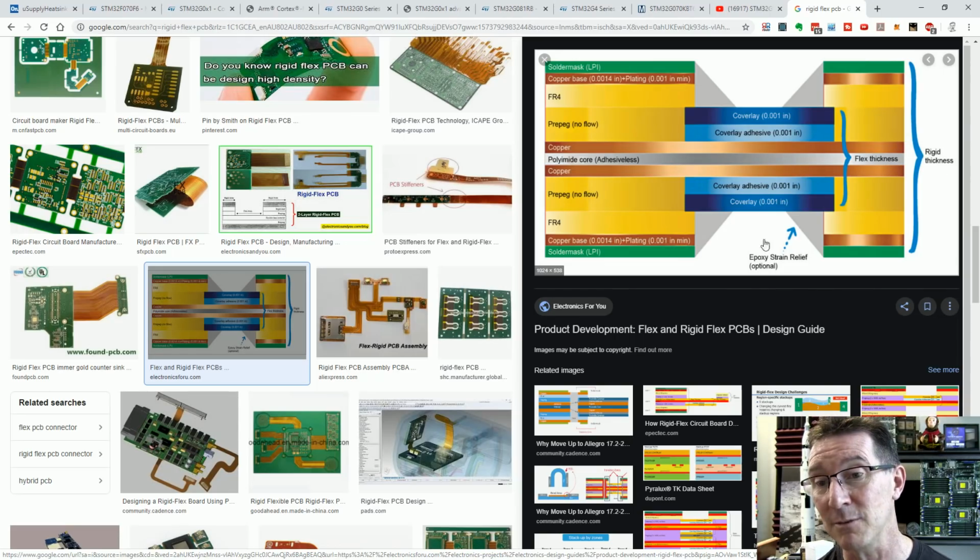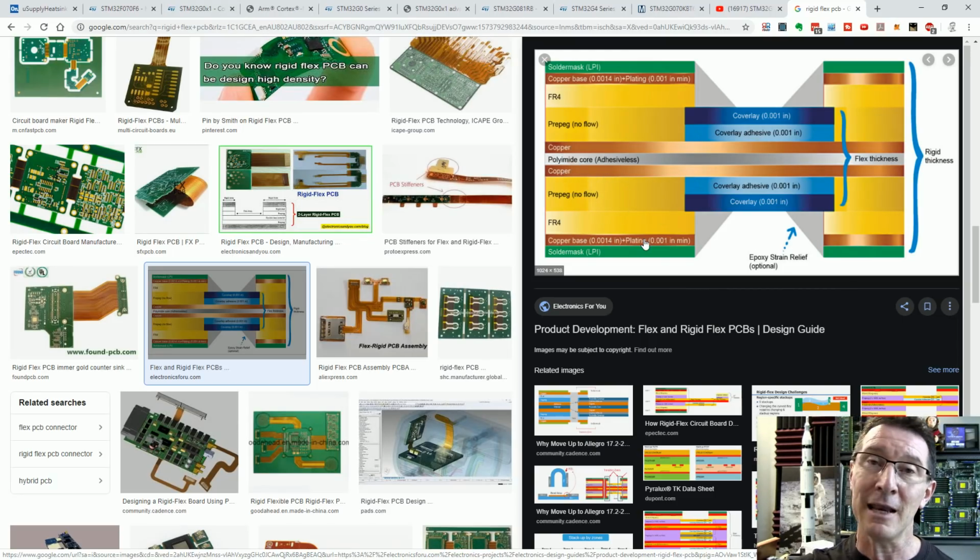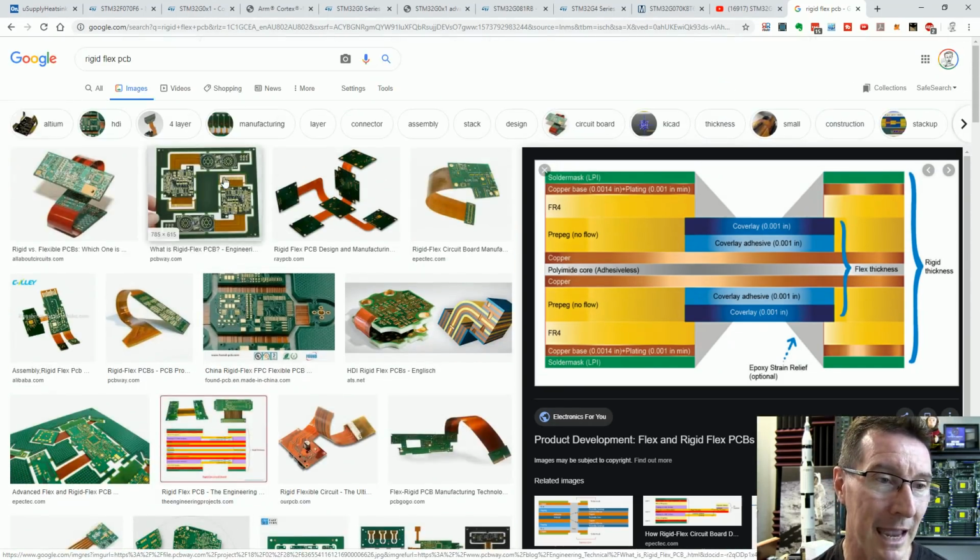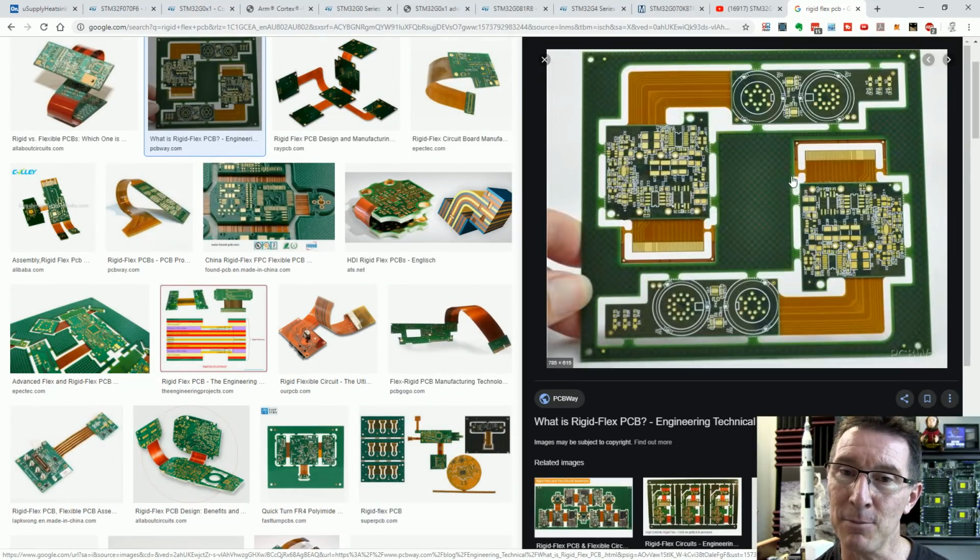But as we're showing on the Altium example, we've got that flex on the bottom 2 layers. So this bit copper here and this copper here are manufactured as a flex. Then they manufacture the FR4 fiberglass ones separately, and then they'll stick those on the top. And it's generally nicer if you do it as a big panel like this, for example. That one's only got 2 separate boards, but you can see how they've designed those as a flex. And that one's got a little LCD connector or something, some sort of ribbony thing at the bottom. And they've got some mouse bites on there. So that's quite a nice design.